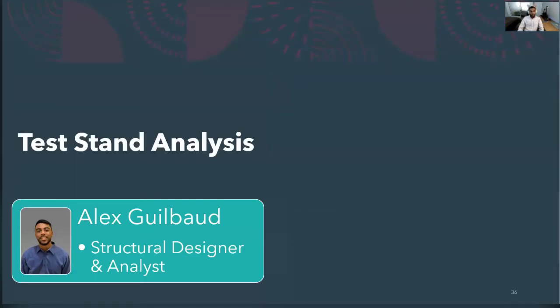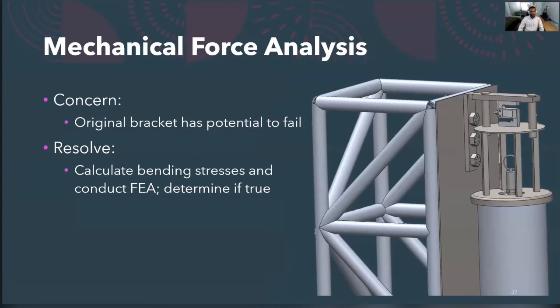Hi, I'm Alex, and I'm going to be discussing the design improvements to the rocket structure. Since optimization and improvement was the main focus of this semester, I'll start by analyzing the primary area of concern of the structure from last semester, which was the load cell compartment. The design consisted of a sliding type of mechanism to which the motor assembly would be guided up the two rods shown, ultimately compressing the load cell and giving us a force measurement.